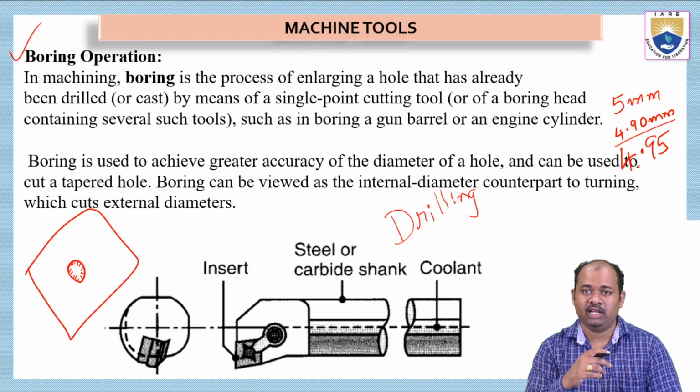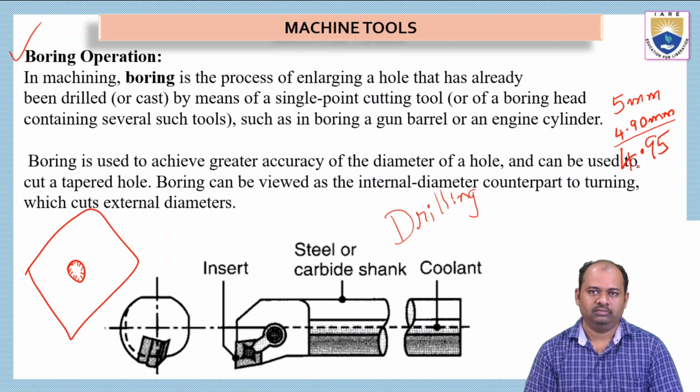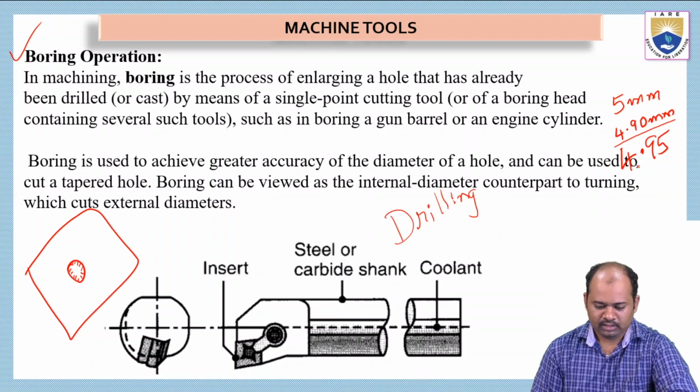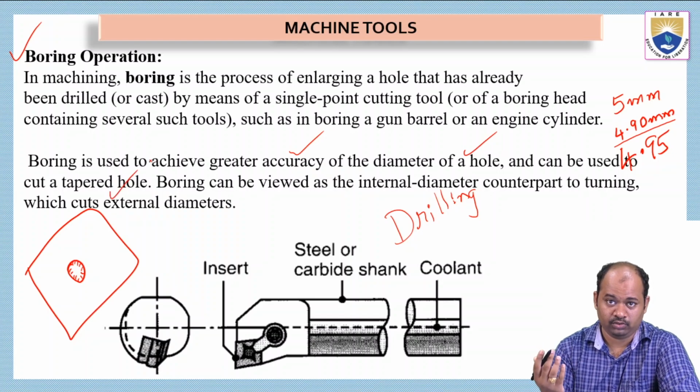The boring operation has to be done in order to increase the surface smoothness of the hole, and also it can increase the dimensions. So see this, boring is used to achieve greater accuracy of the diameter of the hole and can be used to cut tapered holes also.